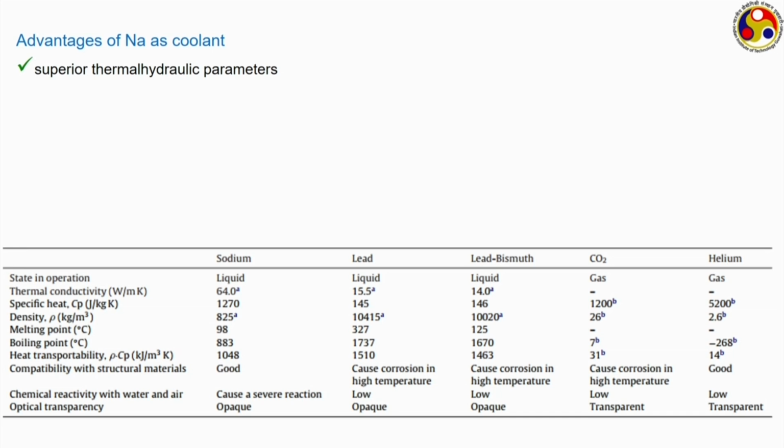So, considering all these points, sodium has superior thermal parameters, and apart from the boiling point, once we can restrict the highest temperature, it is definitely a more suitable fluid compared to lead.